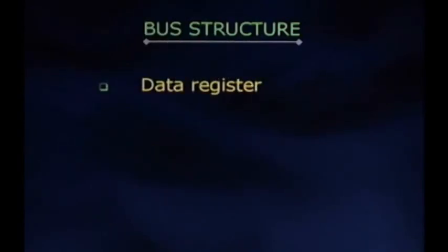The next register is the data register. The data register stores the data for many applications. The data to be entered into memory or the data that is read from memory are the data items usually stored in this register. The contents of the data register may be transferred to any other register under program control with the help of the bus structure. The data register will also have the facilities of clearing it to 0, incrementing the register contents and loading into the register from the system bus.